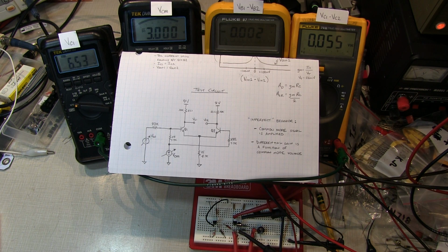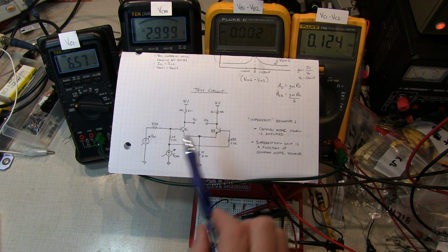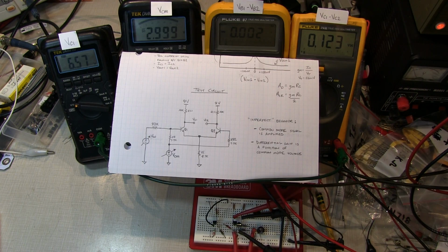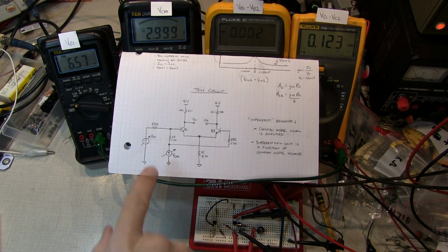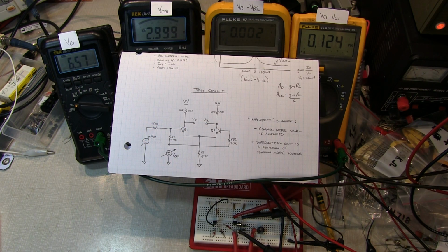On an integrated circuit, this typically doesn't matter because the transistors are very closely matched thermally and in performance and everything else, so it's really not an issue. And of course, when building diff amps like this in discrete circuits, oftentimes you're employing feedback, sometimes in the form of emitter degeneration or elsewhere, so that these mismatch issues don't become an issue. So let's apply our input voltage to one side here to start changing VB1 with respect to VB2 and see how that changes the output voltage.